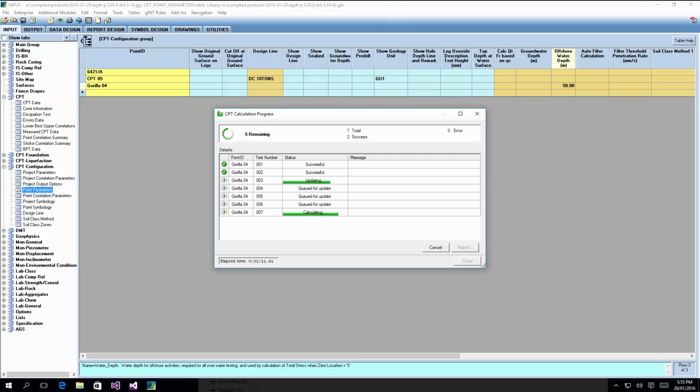Now, you'll find that there's a lot of calculations happening at the moment, many of them just irrelevant to what you're doing. Like the liquefaction doesn't really apply, and some of it doesn't quite work when you've got all these multiple strokes. So that can be turned off by going to the add-in CPT tool, formula tool, and unchecking the boxes for the ones you don't need. I won't actually show you that now, but you can look at the user guide to learn about that.